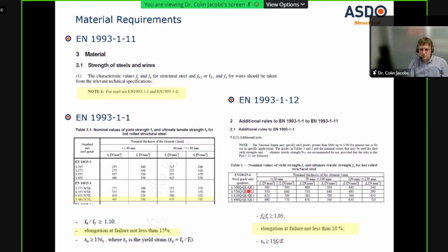So again, we have the gross area of the section, the yield value of the material, the partial factor. This is a minimum of that, and 0.9 times the root area, and the ultimate stress and the material factor for rupture. Again, the Eurocode is very similar. So basically they are the same equations, with some different nomenclature, but the main difference is your calculation of the thread stress area. Your partial factors are different. You have 1.1 for yield in the Indian codes, and the Eurocode is 1.0.